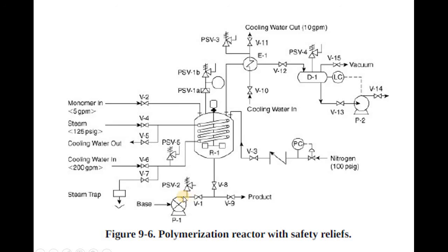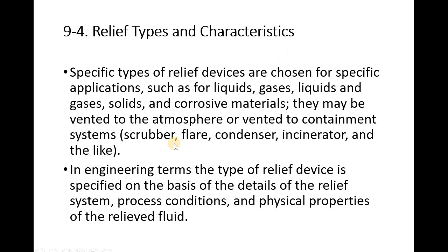And for the head pump, you see the discharge here. Just in case that this is blocked or that is blocked, we have what? We have a process valve here. And what else? If we have build up of pressure here, what do we have? We have, you see the safety valve here, PSV1A and PSV1B. So we have two safety valves here as well. What else do you have? We're going to come to PSV5 in a moment and PSV4, okay?